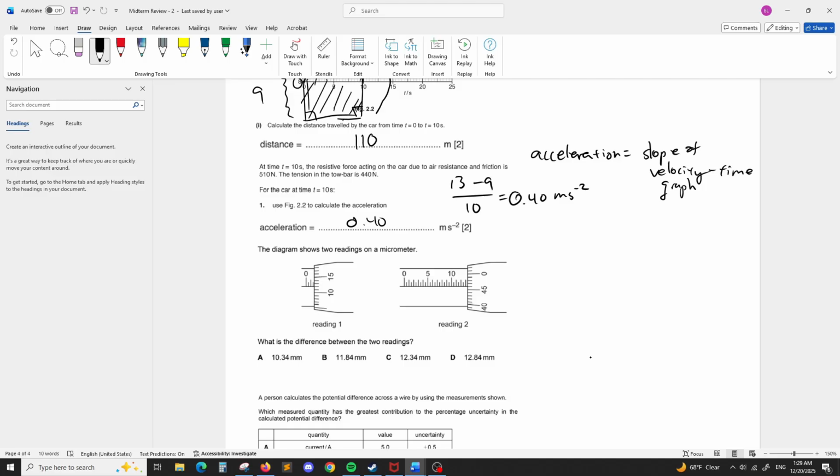It's really straightforward. So basically what you do is you take this part here, the tick mark, the part of the tick mark that you can actually see, and I think that's your pre-decimal place, or your 10th digit in this case. So if we look over here, our 5 is here.